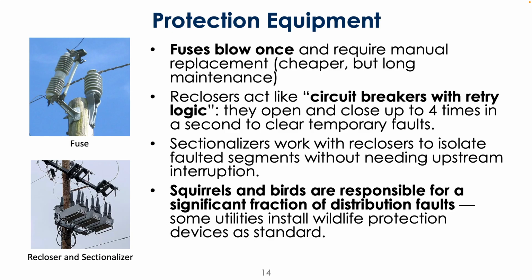Yeah, so the sectionalizer literally counts the number of times the recloser is opening and closing, and it basically says, oh, if you, I think the rule is 4. If you open and close 4 times, usually it will tell the recloser to essentially stay open. And would the recloser that's opening and closing be upstream of the fault or downstream? Upstream. Okay. Yeah, because downstream, you're already too late, right? Whatever's happening up there may not even reach you.